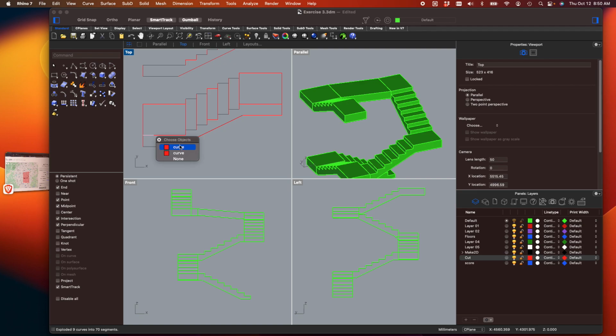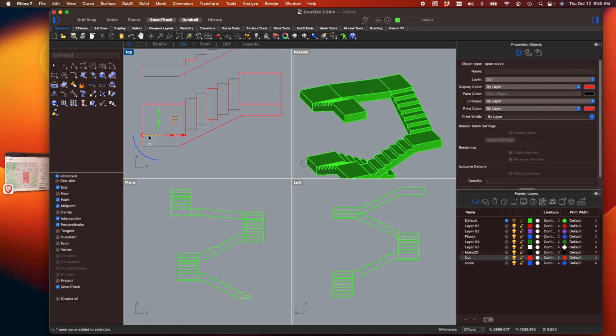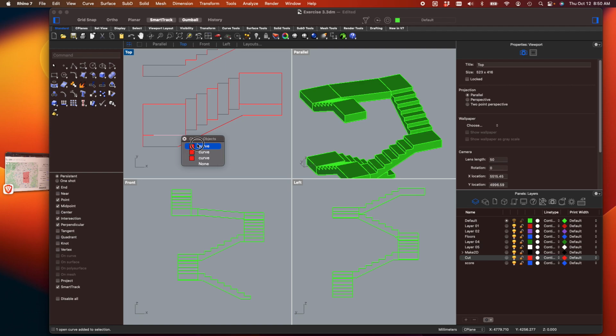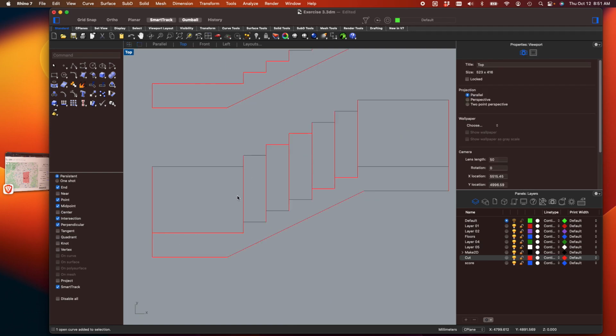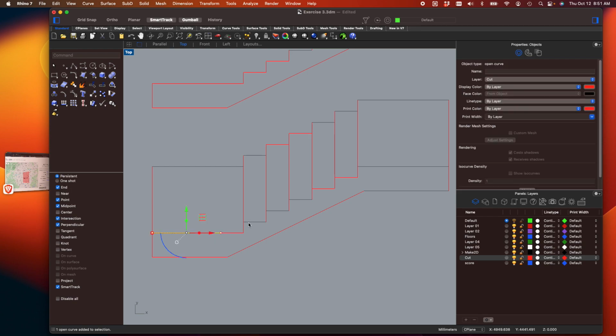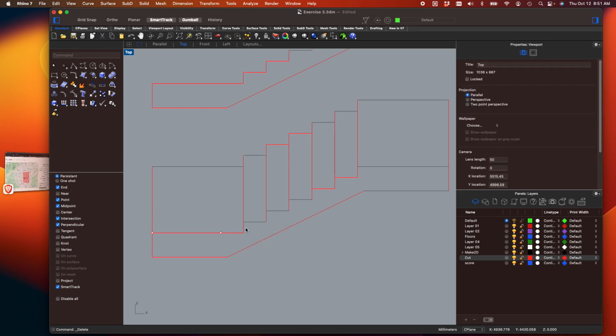Right, but I have like 2 lines in here, so I might want to actually delete some and get rid of anything that I don't need, because that's going to make the laser cutter move a lot slower because it has to perform more lines. For instance, yeah, getting rid of some of these that of course have 2.